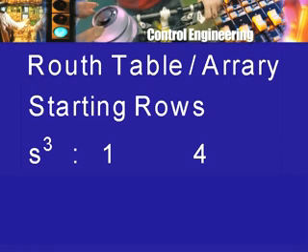So, this is the first row of my table that I am going to write, s cube here, 1 and 4. Now, the textbook may tell you do it this way, but if you do it this way without understanding what you are doing, then it is not really worth learning the whole thing. What you are doing is, from the polynomial, you have separated out its odd part, and this is just a compact way of writing the odd part. The s cube tells you that this 1 is multiplied by s cube, and the next number 4 tells you that 4 multiplies the next lower odd power of s, namely s to the 1. So, s cube, 1 and 4, from that I can conclude that the odd part is 1 into s cube plus 4 into s.